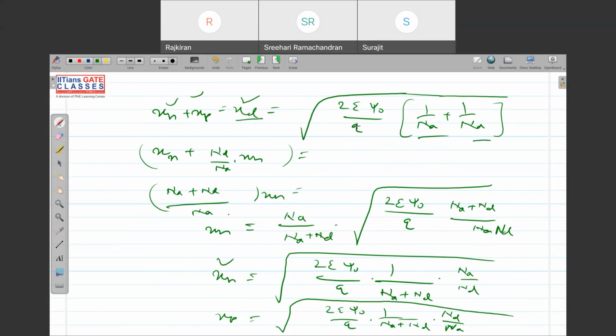So that's why if I go to higher and higher doping, the depletion width should be less, right? Because in a smaller distance I will see more charges per unit volume. So I'll generate the same amount of electric field to oppose the diffusion force, even if I uncover a smaller distance.